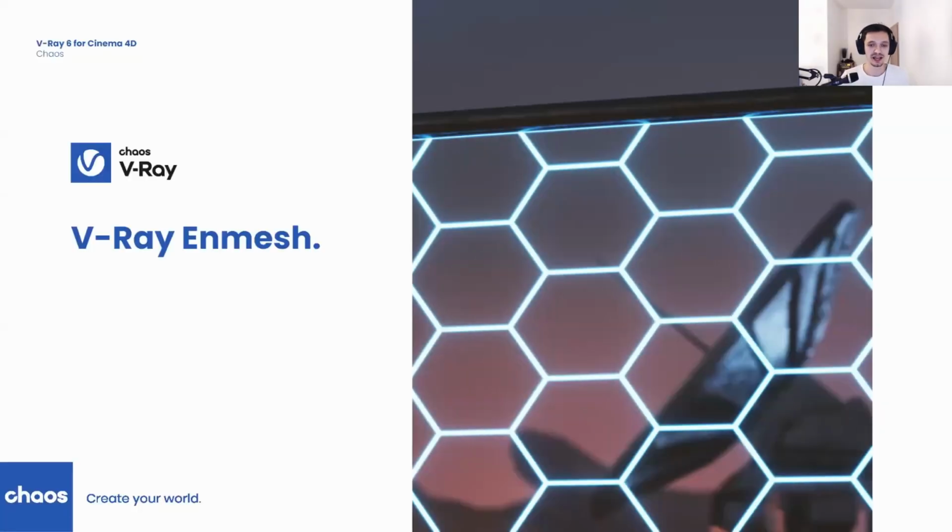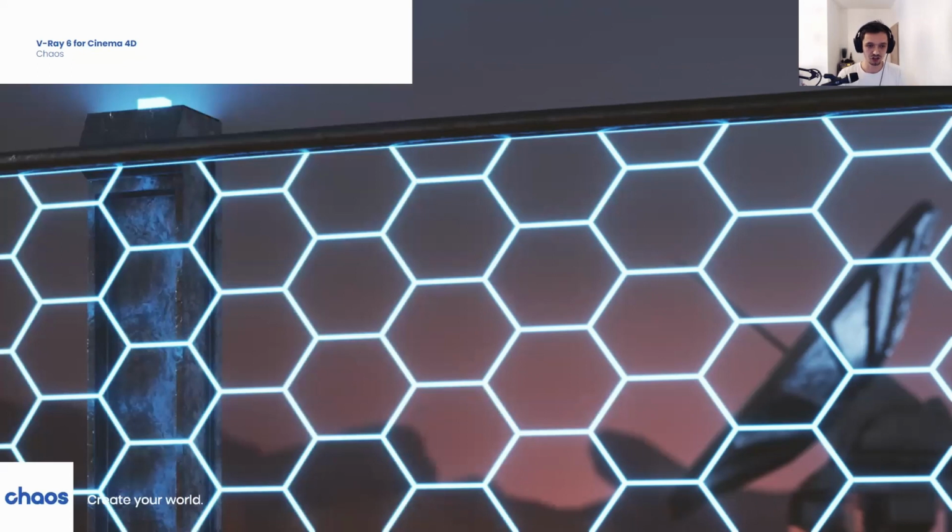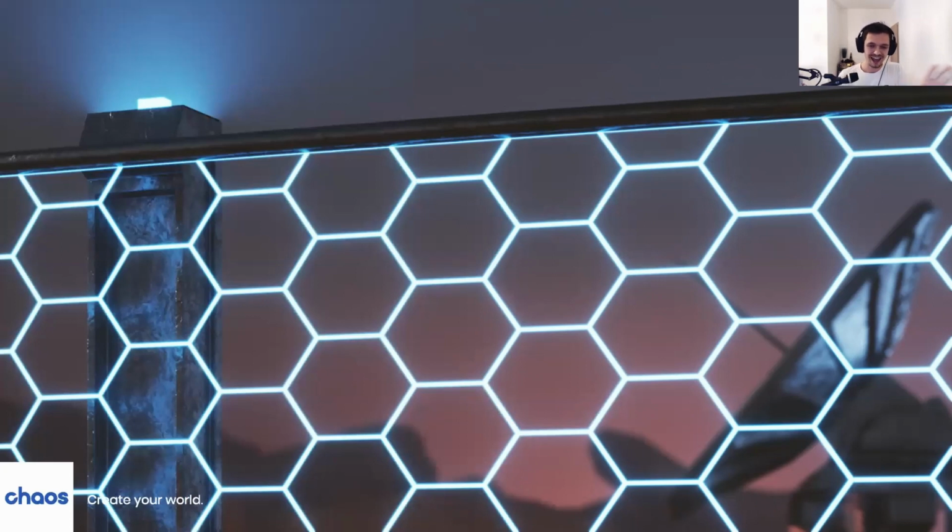Next up, we have V-Ray Enmesh. V-Ray Enmesh makes tiling 3D geometry onto surfaces real easy. All you have to make sure is that you have your surfaces unwrapped accordingly. In this case, you can see that this n-gon pattern is being spread out in a fashion so that it looks like a fence. And we've done that with Enmesh.